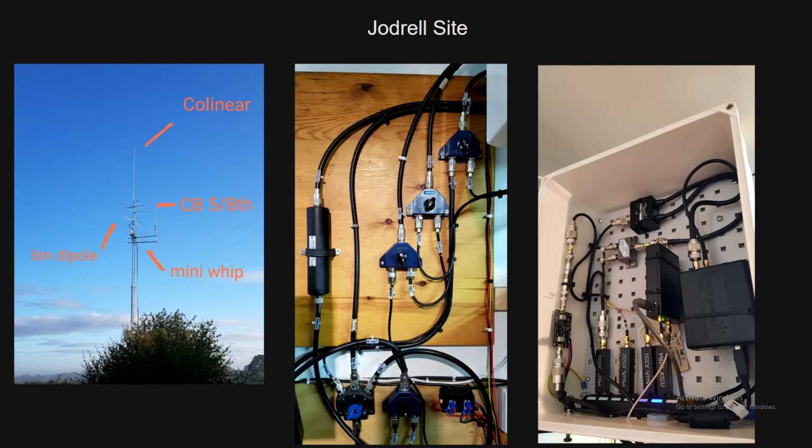That comes down into various switches, so I can switch between my own shack radios and the actual WebSDR. So sometimes I'll transmit and I'll flick these across. Most questions are, what happens with the WebSDRs when you transmit? Well, the simple answer to that is they don't like it. So the best solution would be some form of TR switching, so transmit receive switching, so that you can stop the RF getting into it. Recently I've just killed the up converter because it didn't like 400 watts.